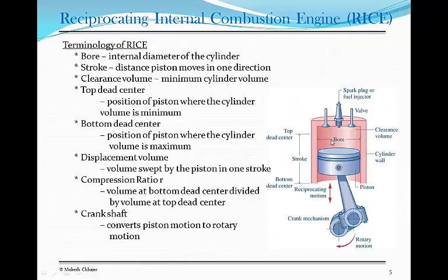The bore, which is right there, is basically the internal diameter of the cylinder in which the piston moves up and down. A stroke is the distance that the piston moves in one direction. So it may be in the beginning right at the top, and then it might go all the way down to the bottom here, or it may start at the bottom and go all the way to the top. So that distance traveled in one direction is called the stroke.